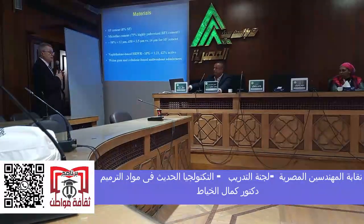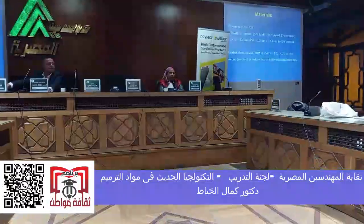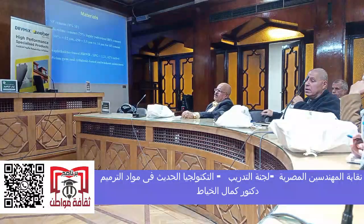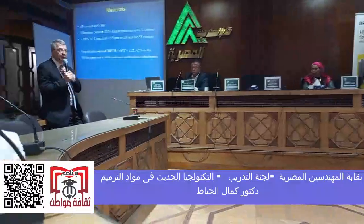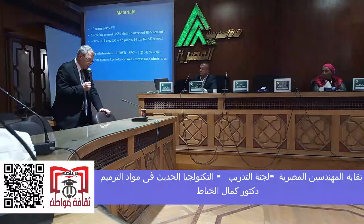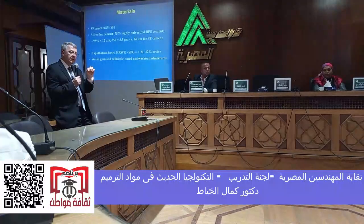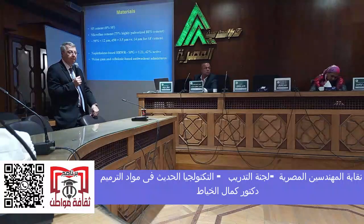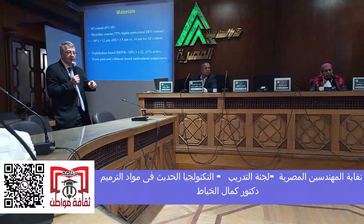So we use the materials, silica fume 8%. Sorry, you said sometimes the mortar blocks. Yes. Why? It blocks because the cement particles are big enough that they don't penetrate the space between the sand particles. So in the sand column test, the type of sand that you use can reflect the crack opening. I think you should use fine sand, fine particles. Yes, and that's exactly what we had to do.